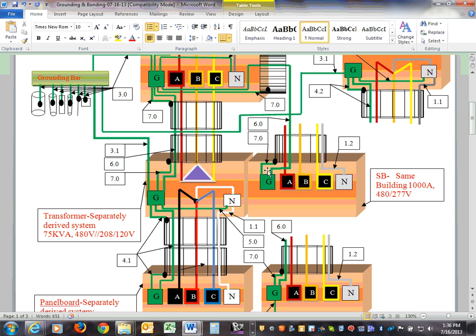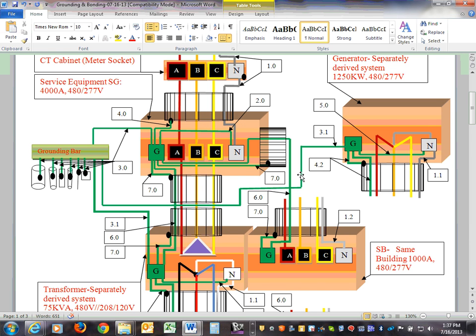Actually, all you need is one side, but it's a good idea to put them on both sides because they will act as an equipment grounding conductor if you have a ground fault. And tie them to, see how that conduit is tied to the other side. Now, guys, if this panel is a 225 amp panel, if you're coming from the bottom of that panel or the top, there are multiple ways of doing the bond.